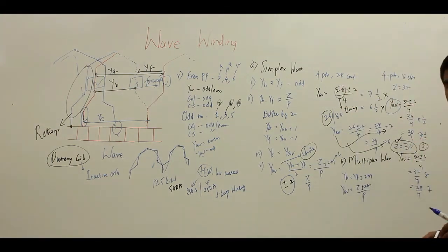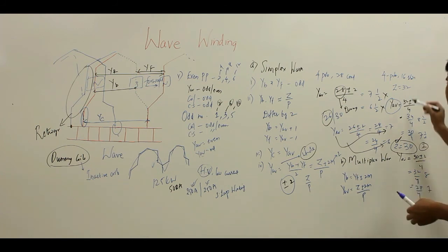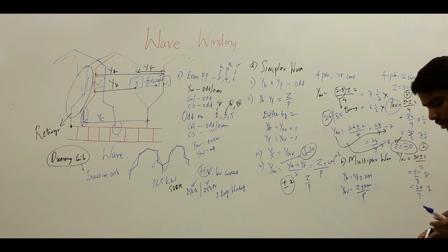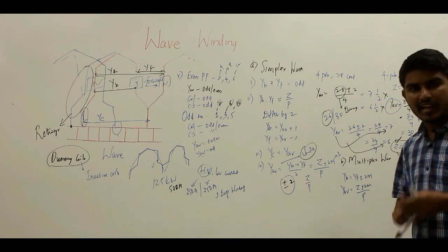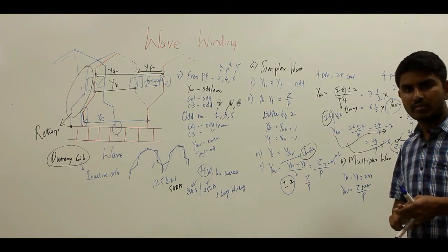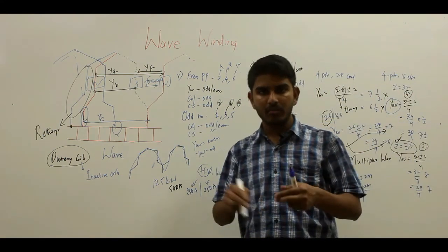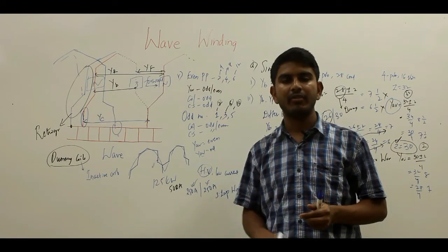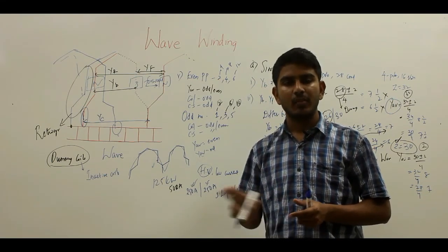But the standard armature punchings available in the armature winding shops will be having the slots for 32 conductors. Now what you can do with these two conductors, you have to make these two conductors inactive, so that these two conductors won't come into picture. So for these two conductors, you tape them and you keep them separated from the electrical connection, or you can say separated from any connection to the commutator segments.